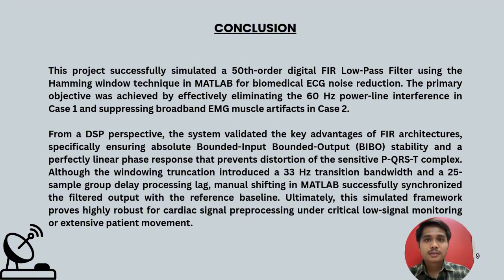Of course, there was a trade-off. The windowing transition introduced a 33 Hz transition bandwidth and a 25 sample group delay. However, we managed to solve this processing lag by applying a manual shifting in MATLAB to synchronize the filter output back with the reference baseline. Ultimately, this simulated framework proves to be highly robust for cardiac signal pre-processing, especially under critical low signal monitoring or intensive patient movement. That's all from us.